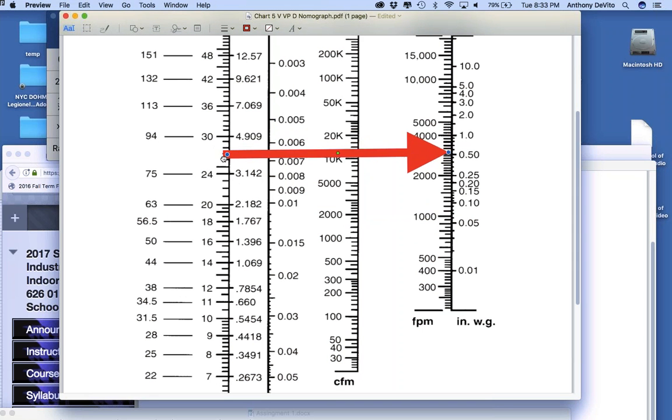As you reduce the size of the ductwork, right, the K factor goes up. As you increase the size of the ductwork, even with the same velocity, you're also going to get a smaller K value as well, right? Because in a circle, you have this big a circle, you have this smaller circle, a lot more of the air is in contact with the side and being affected by friction.